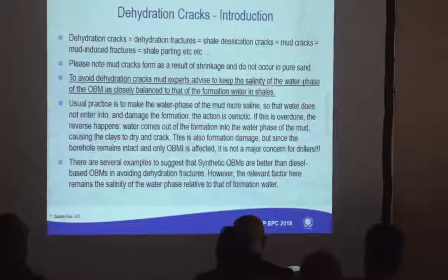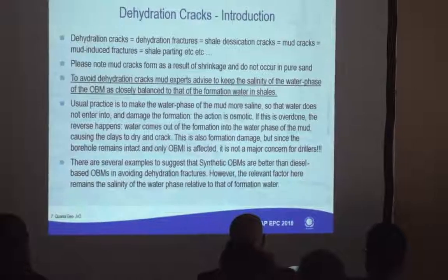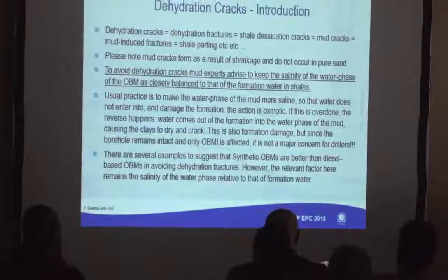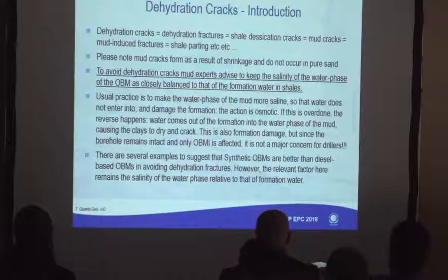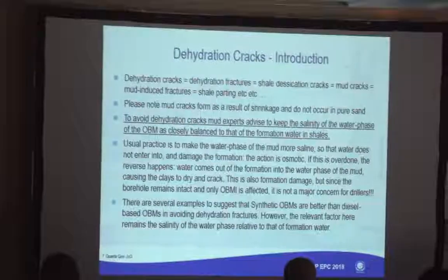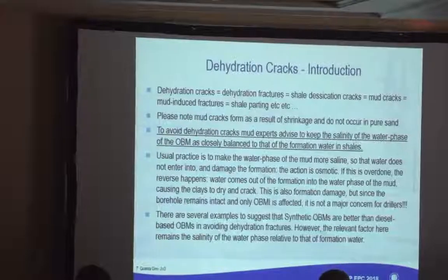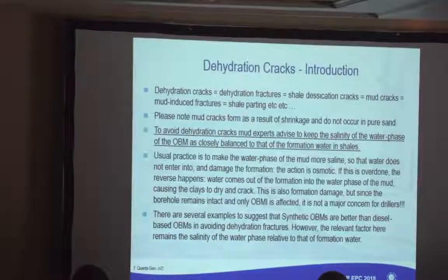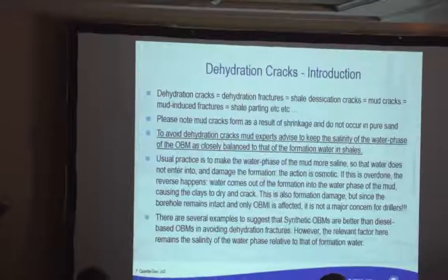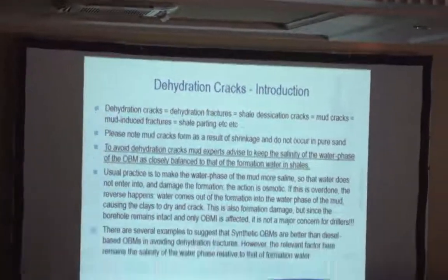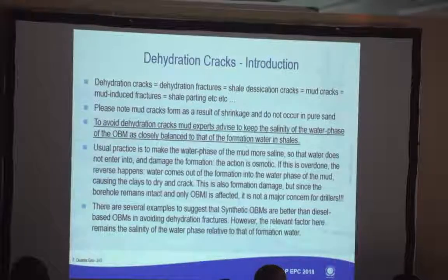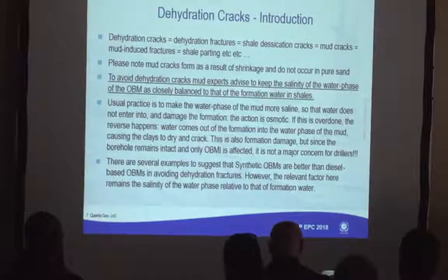And an oil-based mud has a water phase and an oil phase. And that water phase you try to keep rather saline to prevent the water from entering the formation. That is common practice. Now if that water phase is too saline and it comes into contact with formation water, you know what will happen. There is an osmotic effect. And what actually will happen is that the fresh water from the formation will be pulled out of the formation so as to equalize the salinity between the two waters.